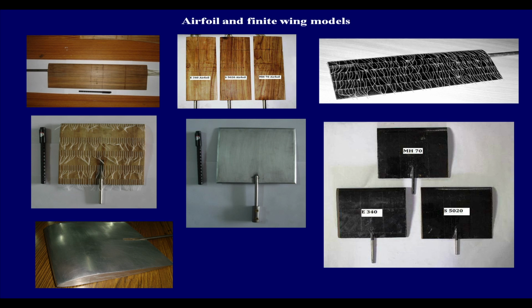Because what will finally happen on the surface, whether it's pressure or whether it's velocity distribution within the boundary layer, is going to be massively affected by those small things happening at those scales. So, we shouldn't undermine the smaller part of the story, it could end up playing a bigger role. So, we have to keep good track of both the overall accuracy of the geometry and the surface finish, and as and when possible work with the bigger models. If you have the liberty of using a bigger model, always go for it, because you have certain advantages.